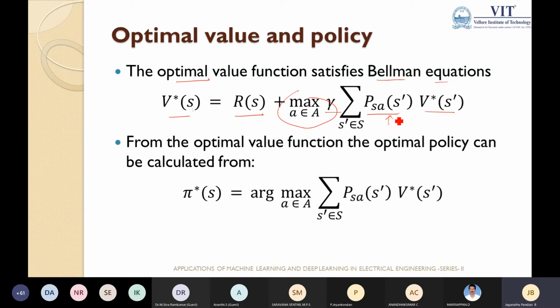If I'm saying there is an uncertain system behavior, a sensor noise, an ambient disturbance, whatever you say, your system will learn that. That is why this reinforcement learned control can be a robust controller also. Not only optimal, it can be robust also. Based on that value function, we use the argmax function. When you are talking about a set or an array, from the set of all possible actions, you select the best one. So argmax is an important function for identifying the optimal policy.